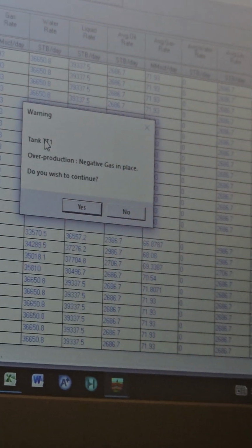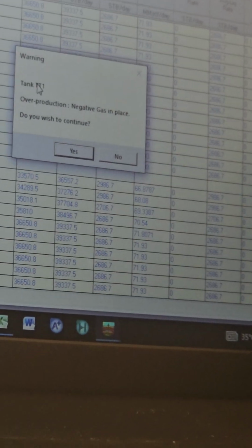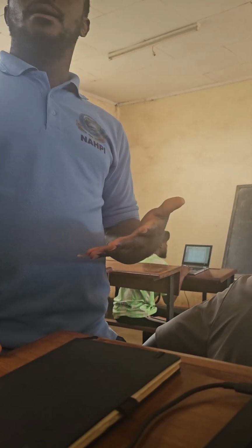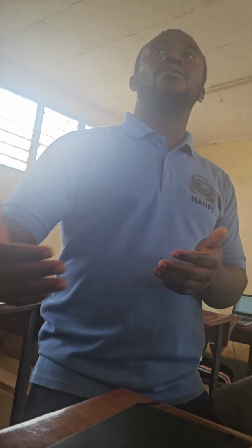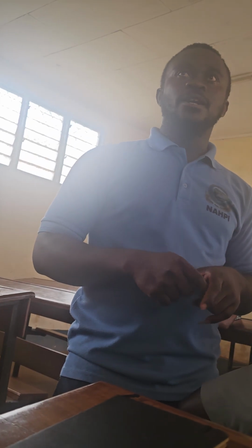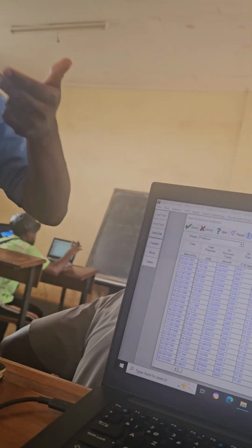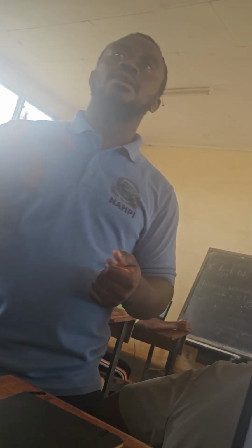Did you take gas injection when you were doing constraint? You model what the reservoir can produce under natural energy to a particular point. It might even show that the fluid within the reservoir is depleted, whereas it's not depleted. It's maybe because of the energy that is depleted. So now you have to go and remodel, checking if they should apply secondary oil recovery or enhanced oil recovery, and that will be under prediction setup.